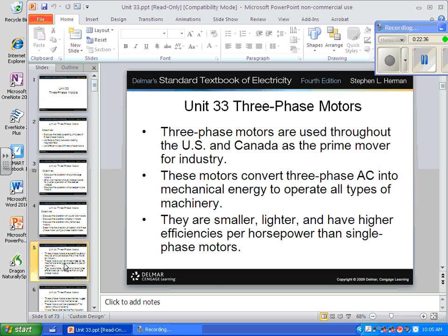But anyway, my friend Bob was working on this place, and he's taking the UPS system off. And he asked me to come over and give him a hand. And I said, Bob, don't you want to phase tape those wires that you're disconnecting from the UPS system? They are three-phase, you know. He goes, no, don't worry about it. No big deal. Well, about a week later, he blew up the UPS system, and he shut down the Navy's payroll system for about a week while he got a new UPS system and installed it and had his insurance company pay for everything. So phase rotation can be very, very important.